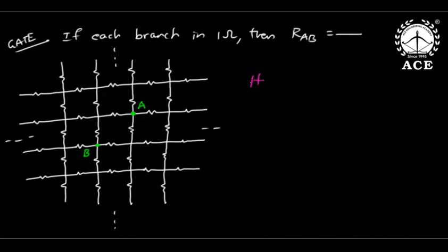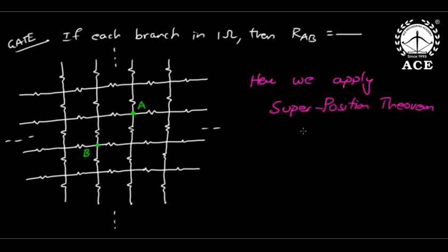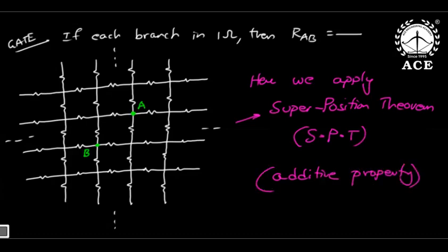Then what to do? Here we apply the superposition theorem, SPT. A wonderful concept. What is the superposition theorem? It is an additive property. What does it say? The effect produced in any element or network when all sources act at a time is also equal to the sum of individual effects.